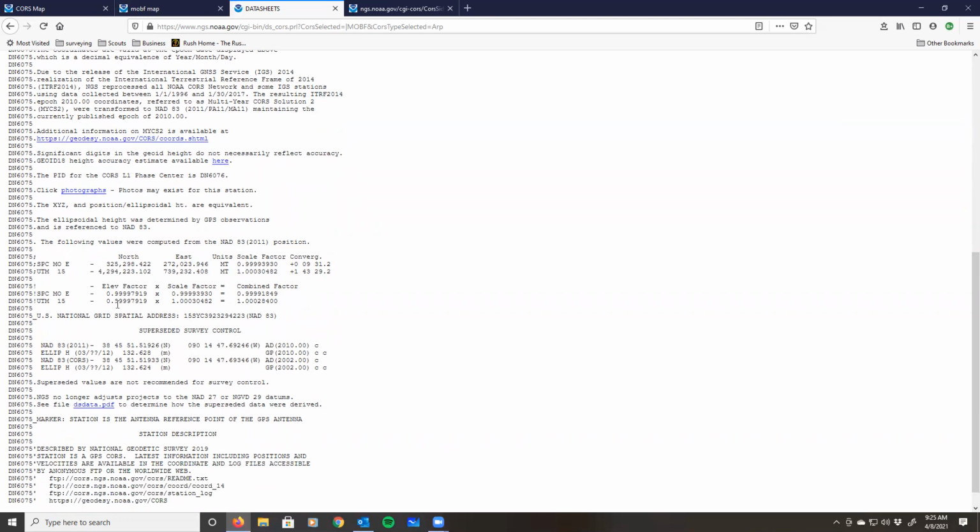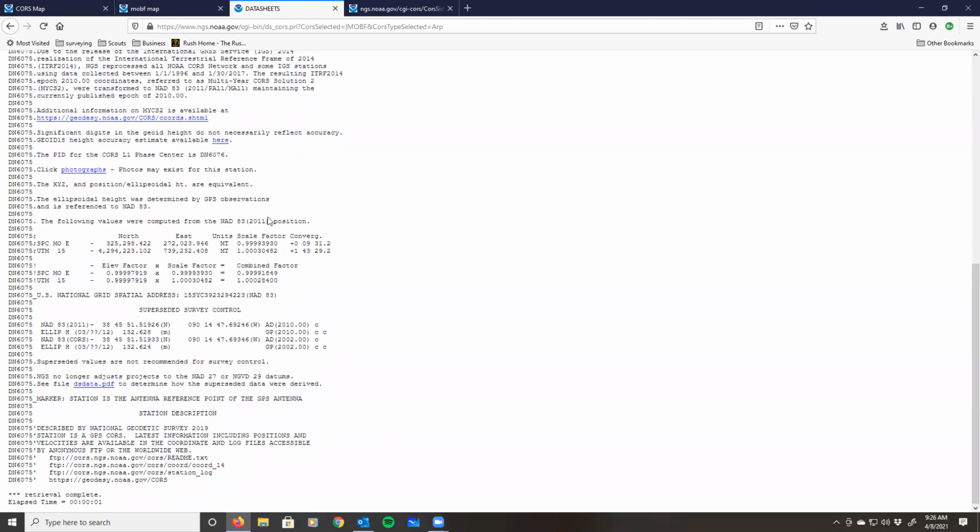We will get into something called elevation factor. The elevation has an effect on the scale factor as well. So here's the mapping scale factor, which is basically right here. The elevation factor is right here. To get a combined factor to convert distances from grid to ground, this is the combined factor that results. And like I said, we'll be getting into details on that later.